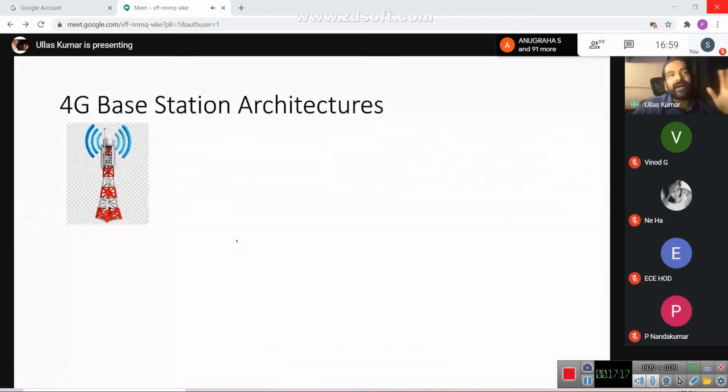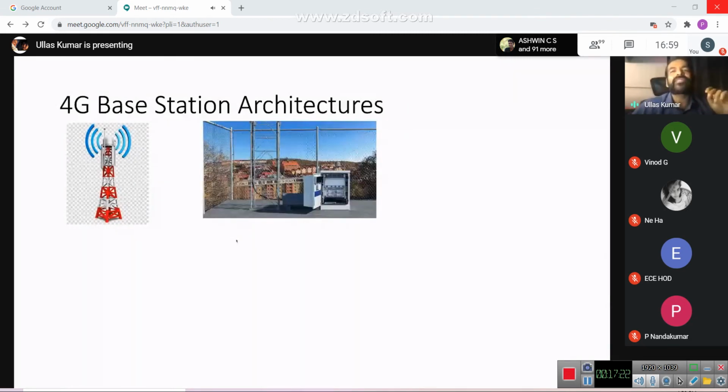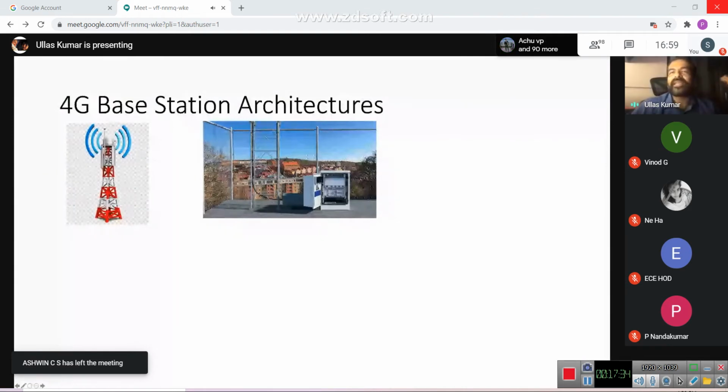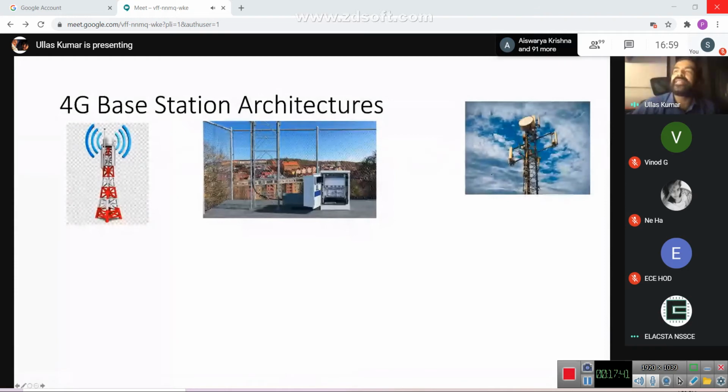So if you look at a base station tower, you will not see something called a base. There is a box at the bottom of this tower that you usually don't notice. That is where all the baseband signal processing is happening. All the network signals come here. It processes the QAM and related things that we discussed here, and then it's sent across through this black cable that we see here into the antennas, like the rectangular ones that we see on the top. You also see this dish-like thing, which is actually the microwave antenna usually used for the backhaul.